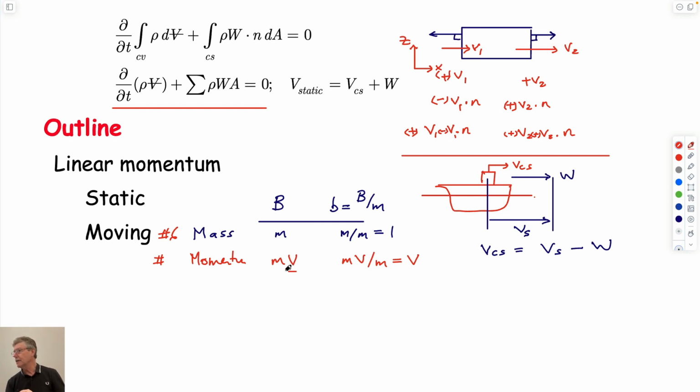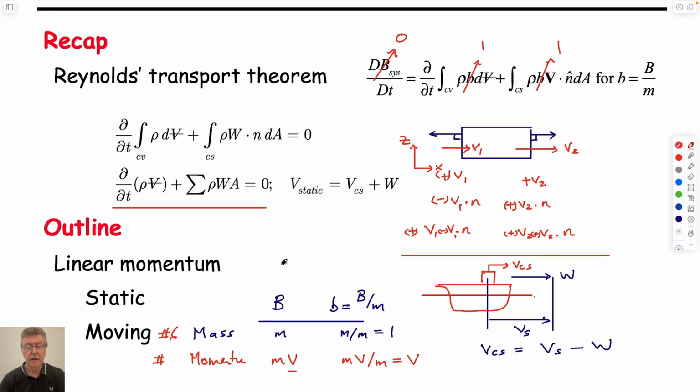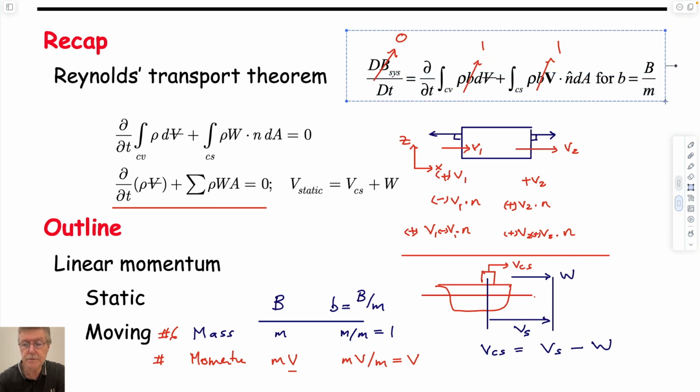Mass rate of flow, because we take the normal to the boundary, it just becomes a scalar value. It's the amount of stuff going across a boundary, normal to that boundary. There is only one direction across the boundary, so it's a scalar. But when we deal with momentum, we're solving Newton's law in x, y, and z, and so we have to be mindful of that. And so what we would do is, if we make those substitutions, so I'm going to make those substitutions.